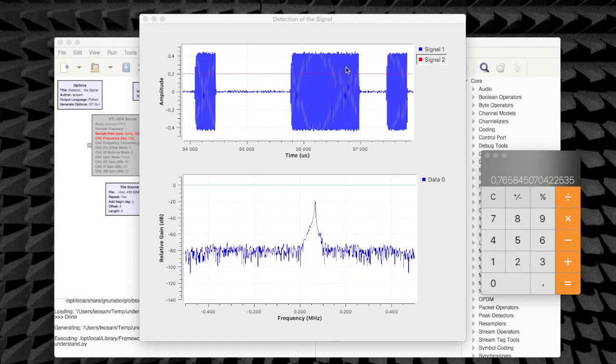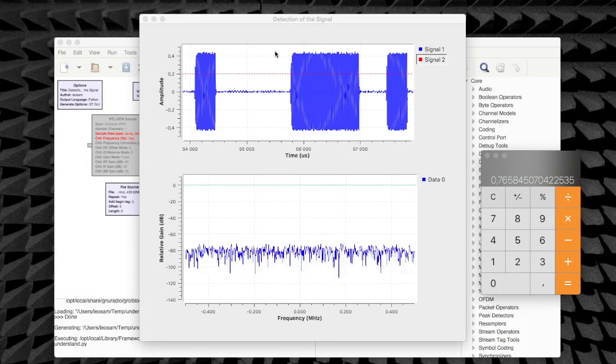Okay? But beware of one thing. I'm saying that this is a 0 and this is a 1, but we still might have some kind of a differential encoding going on here. And in this case, we will look at the switch from same bit to a different bit to decide if the final information is a 0 or a 1, and we'll look at that afterwards when we're trying to decode the signal.